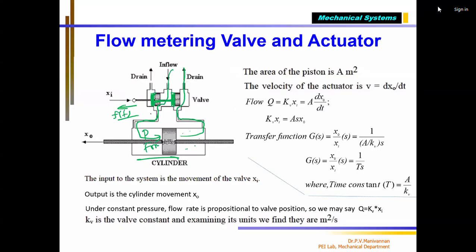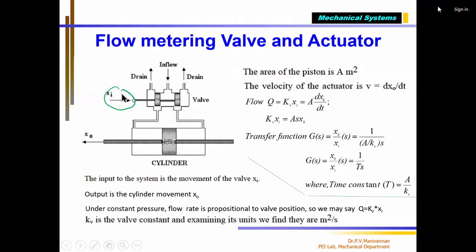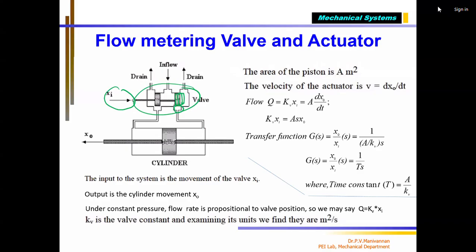So by controlling the direction, how am I controlling the power cylinder? By moving the spool of this direction control valve, correct? And if I move it, how much this is opening, I can move little by little, correct? I can fully open or partially open.